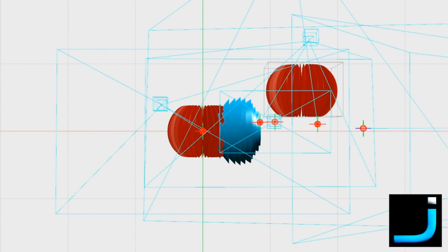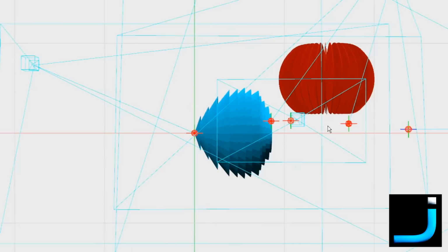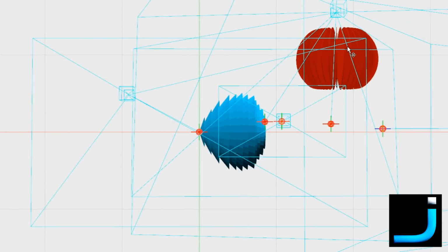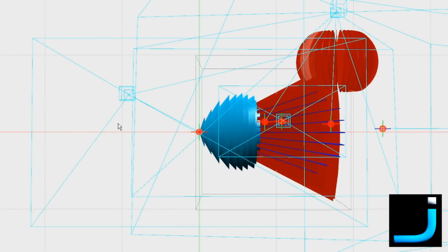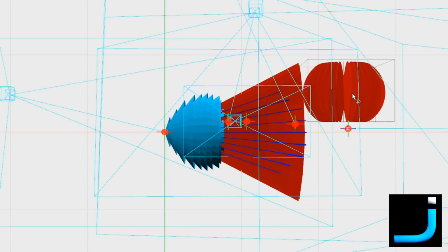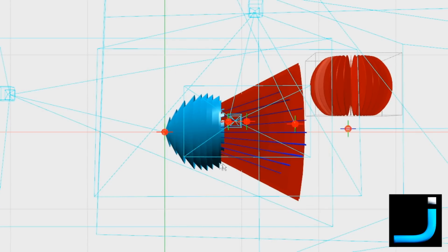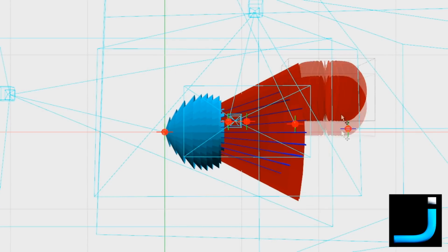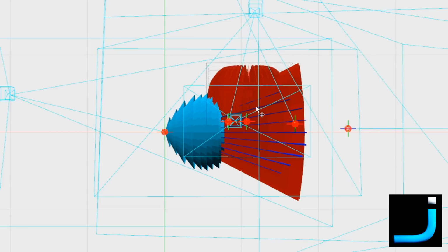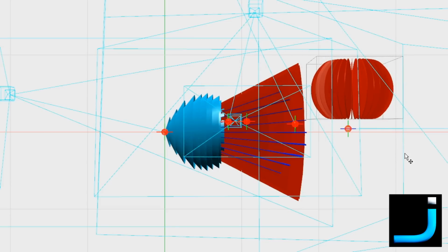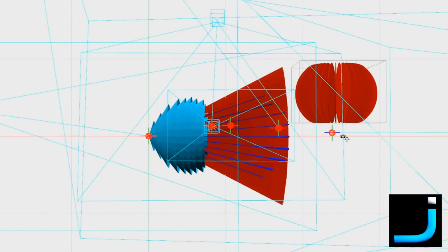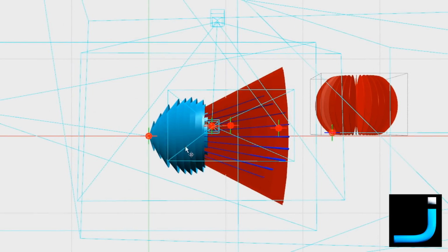So let's turn off the ground station antenna. Let's compare that to the diversity antenna, where we're talking 11 decibel versus 8. So it's slightly higher, so we're getting a little bit further out, but again, with the circularly polarized, it's a much better signal through trees and in your local vicinity. So that's your circularly polarized antenna.